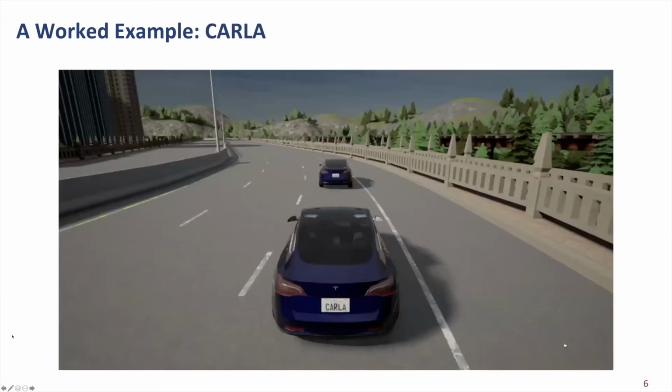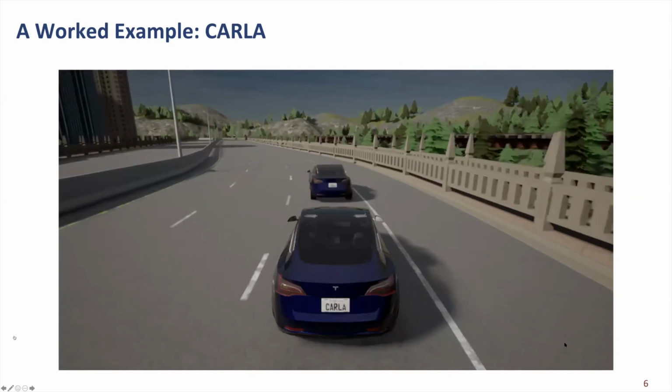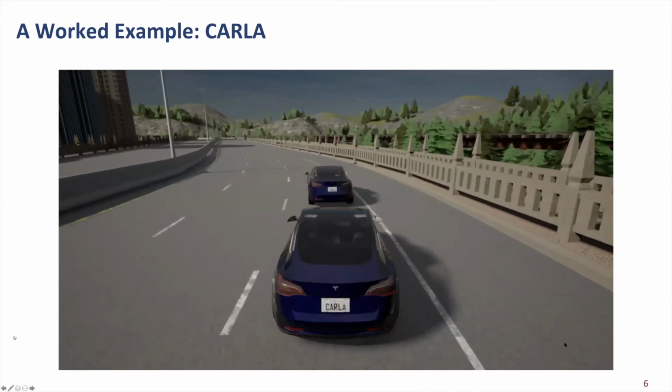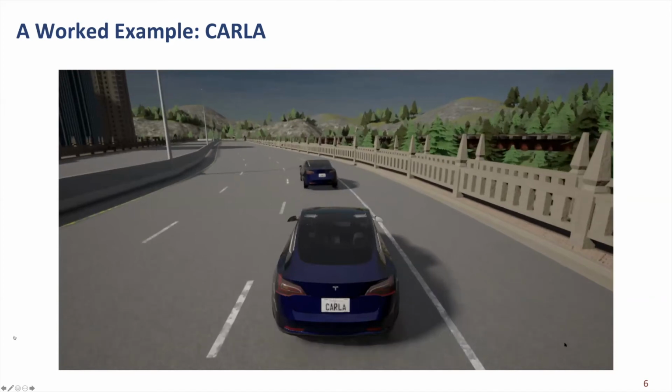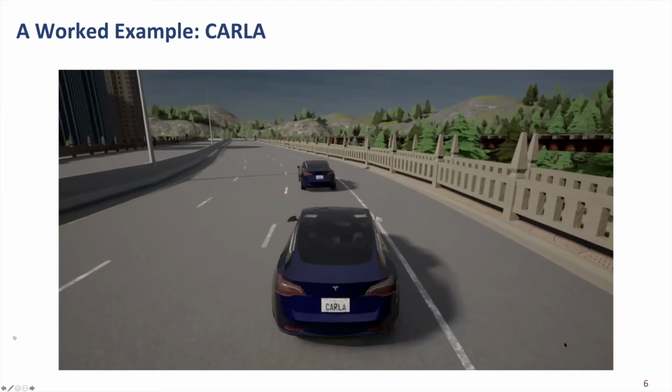Okay, so if we now sample from this scenario, the Scenic tool can execute this scenario in a number of different simulators. So for instance, here it is running in Carla. So you can see the cars start going, the lead car stops, and the ego car successfully brakes. Now, once the lead car starts again, they keep going, etc. So this is just a simple example of a scenario.